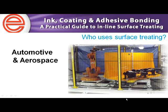Similarly, with exotic materials in the aerospace industry, bonding is usually a challenge, and we have a number of applications which have helped enhance these bonding applications. One that we've seen is potting of cables. So if you're trying to bring cables into a plastic component and use a potting compound to get better adhesion, we can treat the plastic component to ensure they have proper adhesion and those pieces don't fail in the aerospace industry.